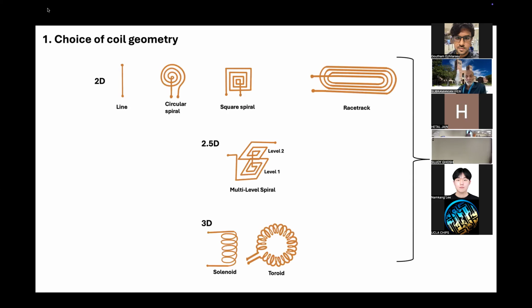When you talk about coil geometry, during my master's a lot of work went into understanding whether, given a loop of wire, there is an optimal way of having a loop that increases the inductance density. It turns out that no matter what complicated shape of a loop you make, imagine some random loop, some of the loops that go one way cancel out with the other way. So there are only certain ways that are the most optimal to make an inductor in terms of coil geometry.